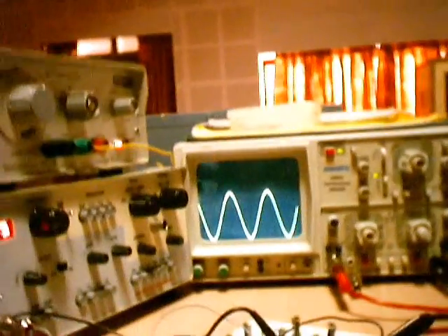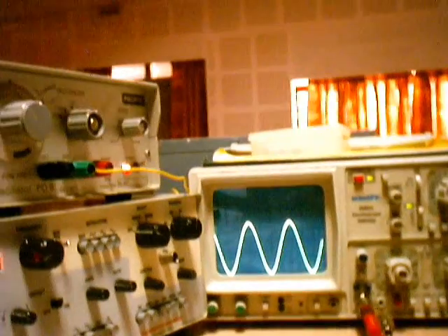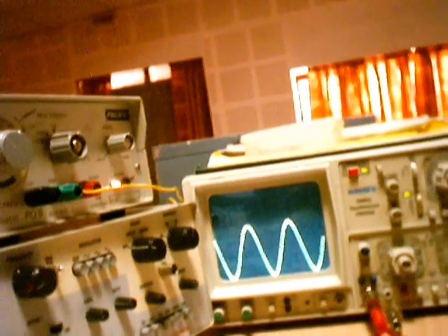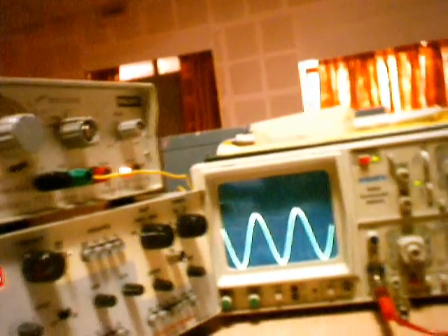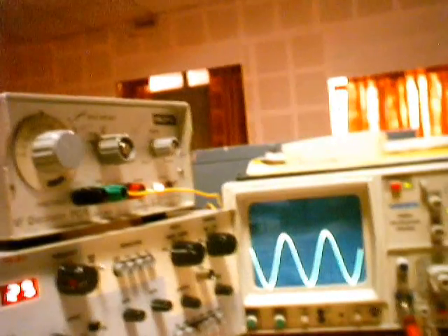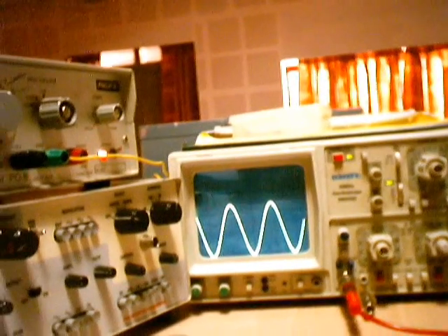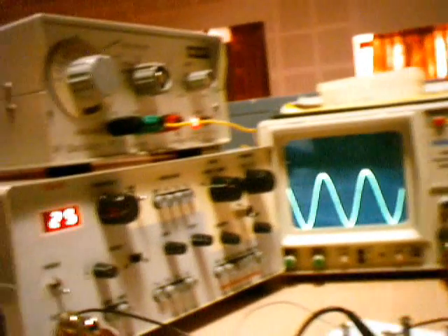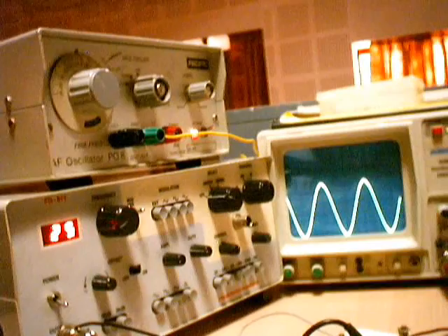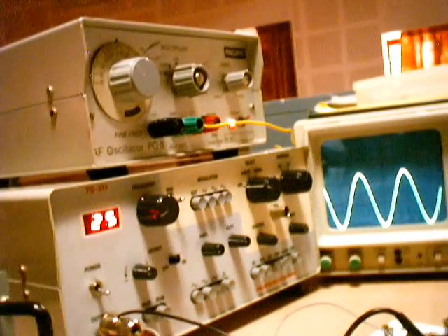We'll see the working of the high pass filter. Here also we are seeing the frequency response of a second order Butterworth filter. Since we are seeing the response of a Butterworth filter, the design gain is 1.586, which happens to be in the passband. So we need to keep the input voltage such that the output is undistorted.